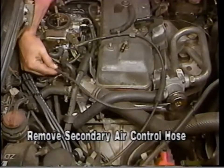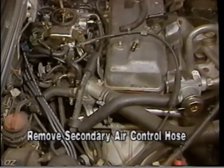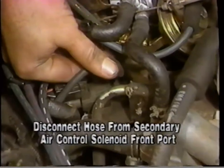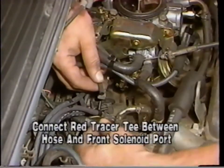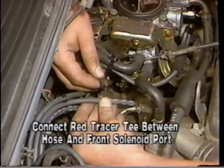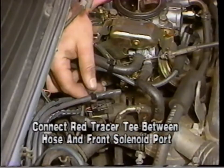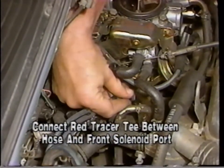Next, locate the vacuum line connecting the secondary air control solenoid and the secondary air control valve, and remove the line. Disconnect the remaining vacuum hose from the secondary air control solenoid front port. Connect the front hose to the T in the red tracer line on the harness. Then, connect the short line from the other side of the T to the front solenoid port.